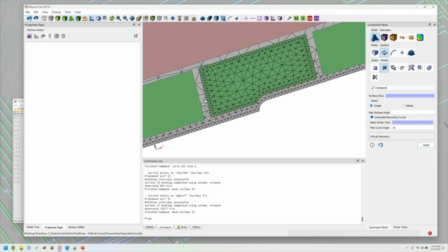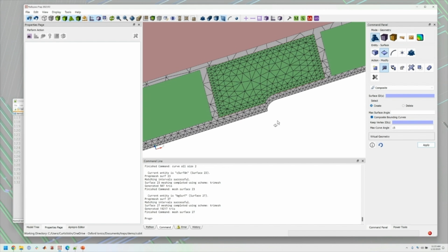And so we want very tiny triangles near the edge so that the simulation is accurately reproducing the physical reality. And we don't need such big triangles in the center because at that location, it looks more like a capacitor, right? We have a uniform charge here, and we can have quite large triangles and be reproducing reality. So the mesher is quite good at simply just telling it what the size of the triangle you want at the perimeter. So in this case, we picked 2 microns, but that's a number you should study for your own particular purposes.